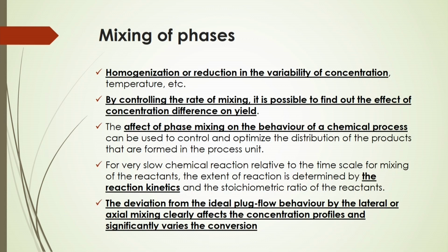But for processes like adsorption, such as gas and solid mixing, if back mixing happens, higher mixing may not give fruitful results. The efficiency of the process may be reduced. So, you have to optimize what degree of mixing is suitable for that particular process.